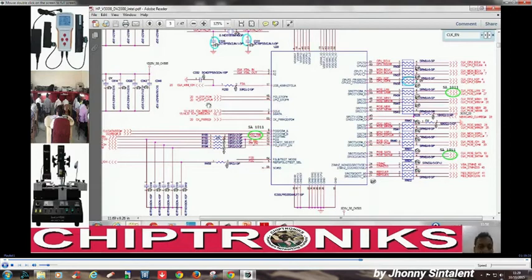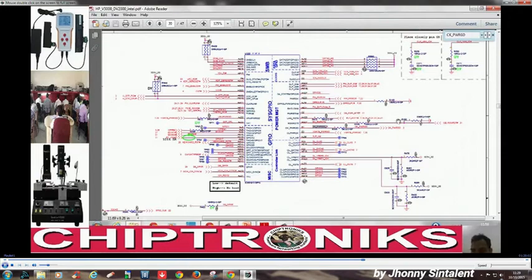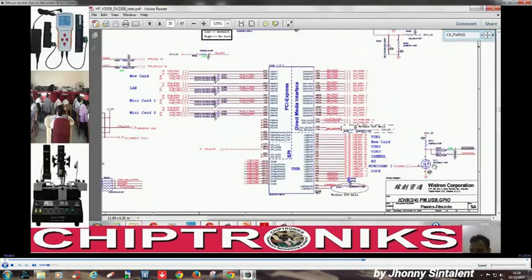This CK power good is generated by the PCH over here. When will CK power good be generated? When the PCH or ICH gets the clock enable signal from the VRM. That is, this clock generator will turn on after the CPU gets power, right? You can see CK power good is generated from here, and the clock enable signal is coming over here, then CK power good is generated.